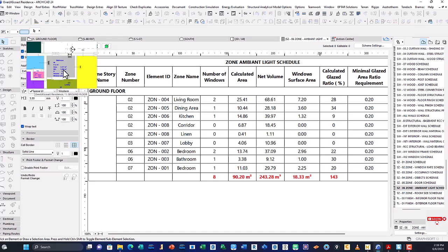Whenever you apply modifications on your floor plan, to your windows, doors, most of your opening building element types, especially if your main schedule criteria is zone, then for this modification made on your floor plan to be replicated automatically by ArchiCAD on your schedule, you need to update your schedule. What do I mean?